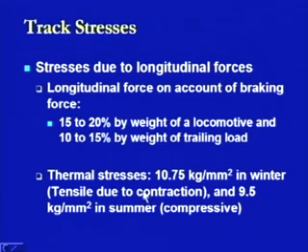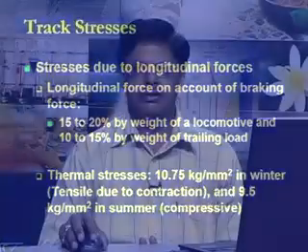The third condition is regarding the thermal stresses. What happens in this case is that as the temperature changes, all the rail sections are laid on the track at a specified temperature. Therefore, if there is a variation with respect to that specified temperature, there will be either contraction or expansion of the rail section.